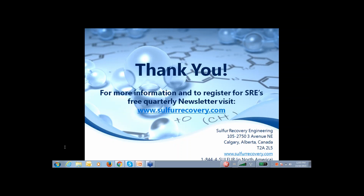Because Titania catalyst is also more expensive than Alumina catalyst, always our bed depth of Titania catalyst would be covered or protected by a thin layer of Alumina catalyst. Essentially we'd have a thin layer of Alumina catalyst covering our primary depth of Titania catalyst, and the idea here is that it's the Alumina catalyst that would take the brunt of any plant upsets that may occur, soot, BTEX that's not destroyed across the reaction furnace.